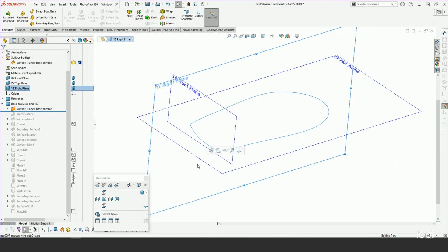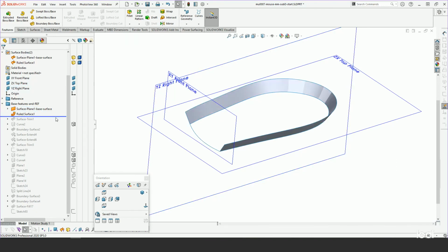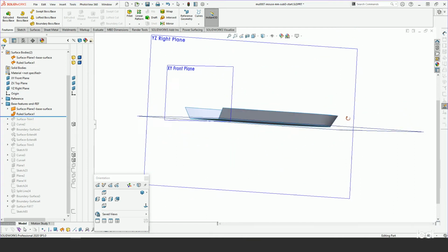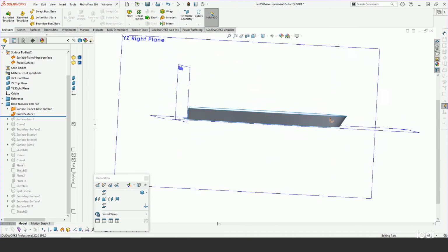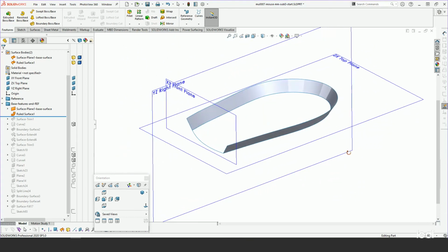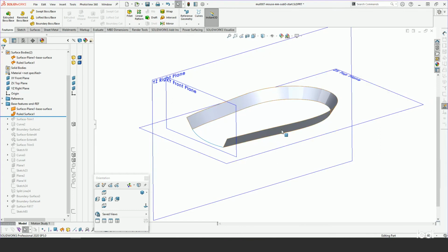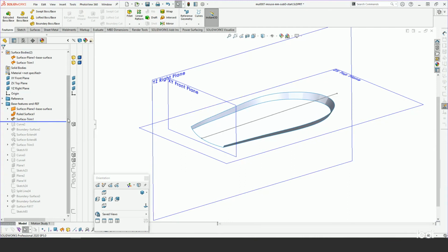From that point, though, there's some other surfaces that are just easier to create in SolidWorks than they would be as a sub-D model. And that would be this ruled surface that's this bottom chamfer. So it's fairly straightforward just to create a ruled surface, add a vector to the top plane, and then trim it back to its side profile, and then create some other reference surfaces.